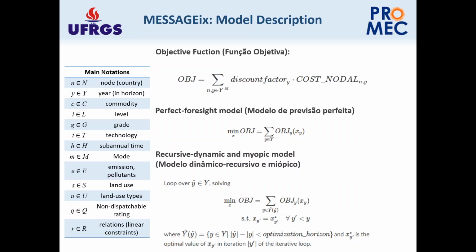You said, if you generate 1 megawatt hour with a gas power plant, you emit this amount of CO2. So you can also have restrictions to say, I want to emit less than, let's say, 200 kilograms of CO2 per megawatt hour. And then you will have to find the best technologies, which is the cheapest to provide electricity with this restriction. For example, a coal power plant emits 800 kilograms per megawatt hour of CO2 into the atmosphere.